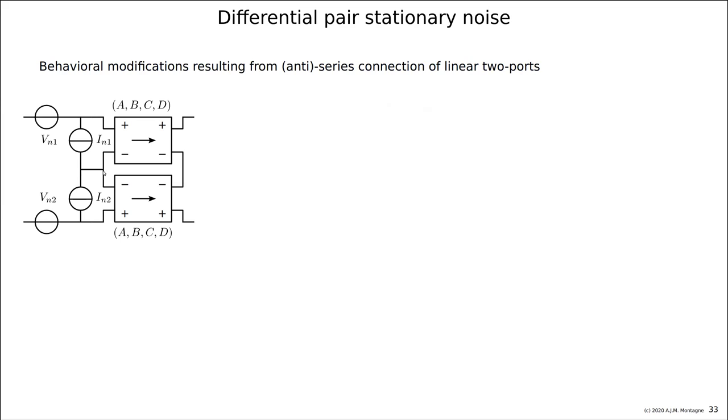And splitting is not going to work. You cannot get rid of it. In fact, we used a not very handy representation of the noise sources for finding the total equivalent input noise. Because you see already at the input, VN1 and VN2 are just in series.